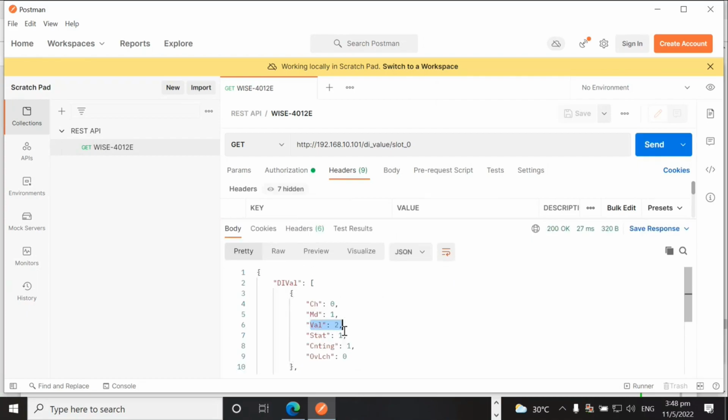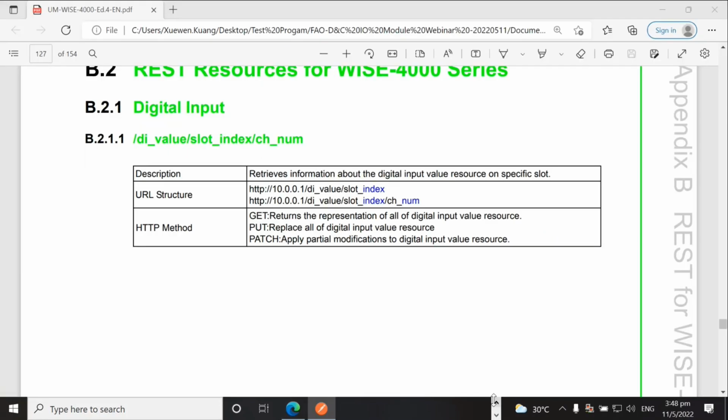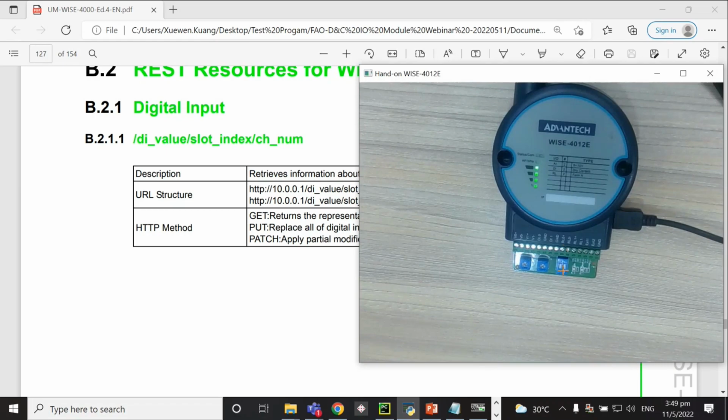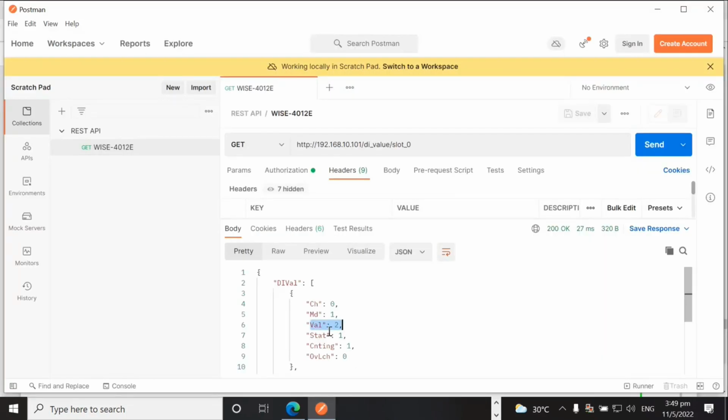Right? I'm toggling, even though I toggle, this one, right? So because of this, you really need to be careful. This also made me confused. Why is it not on? Why is this value returning this? Because our setting is using counter mode. That is the reason the return values are 1 and 2, right? So not 0 and 1. You really need to be careful about this.